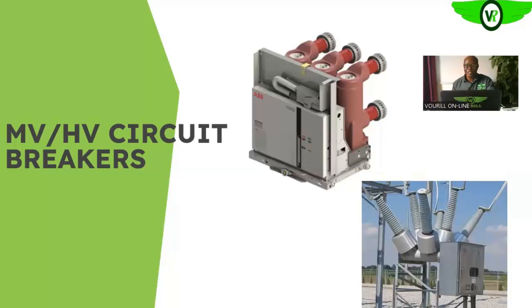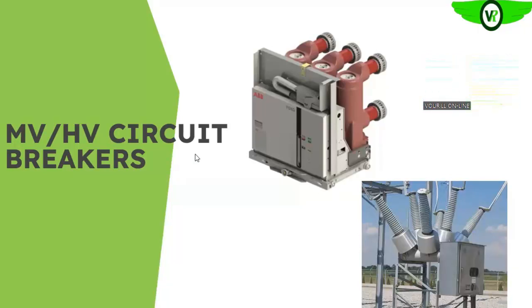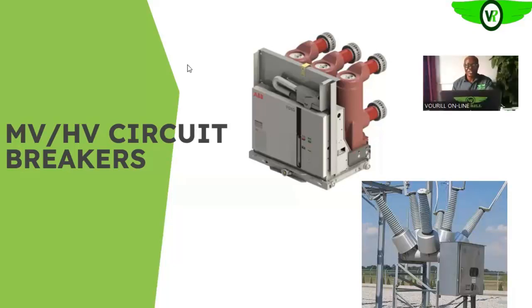As you are moving towards the high voltage environment, the pressure that is driving the current is getting higher, which means that the strength of the arc that will be formed is also increasing. As the strength of the arc is increasing, we need an effective quenching medium to put off that arc as it is being formed. So let us look at how these arcs are formed during the operations of the circuit breaker, during the making and breaking of the circuitry.